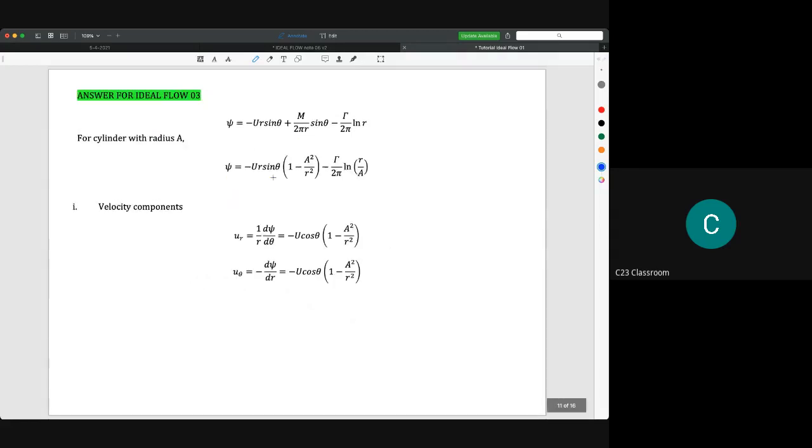So we go for question number 1. As I said, this is the basic idea: to get the rotating flow on a rotating cylinder, we need to merge the linear flow, the doublet, and also the vortex, and finally we could use this term. If you remember this term, you may use it on the spot. If not, you need to prove it step by step. So this is the equation for flow around a rotating cylinder.